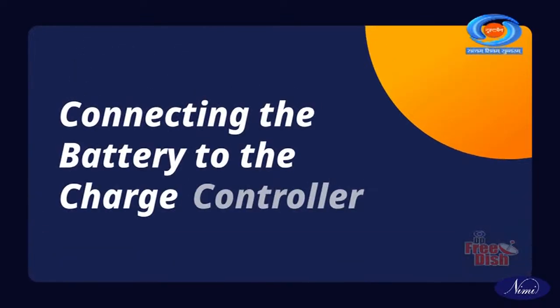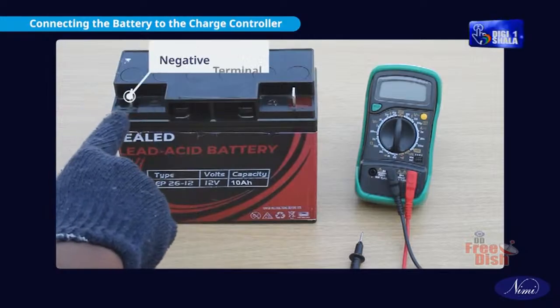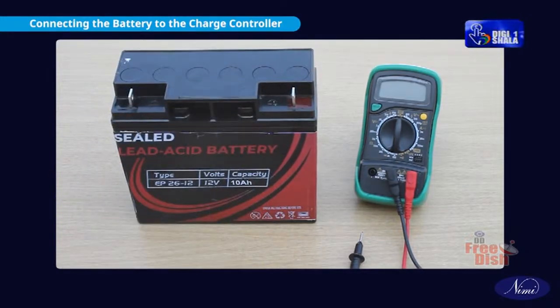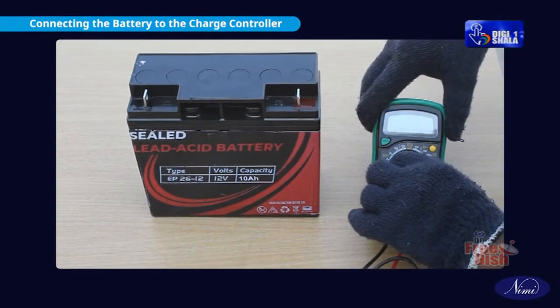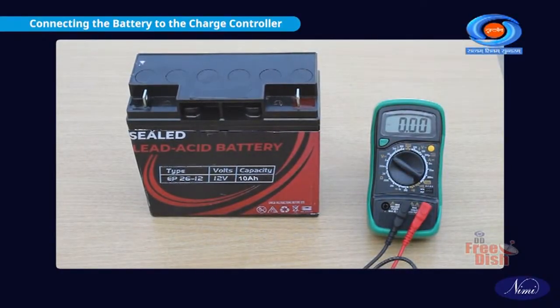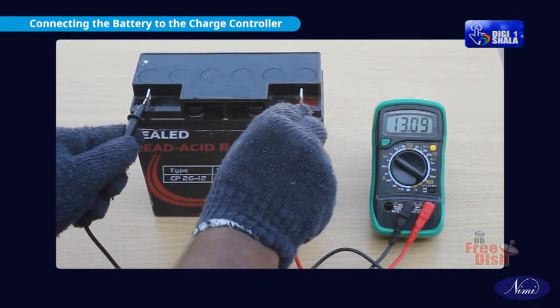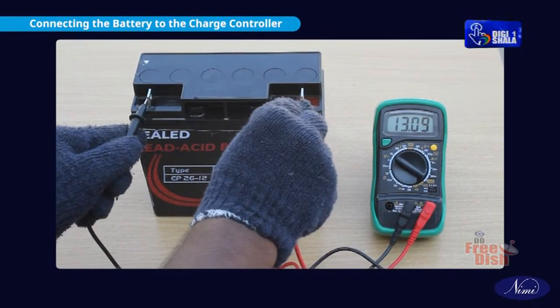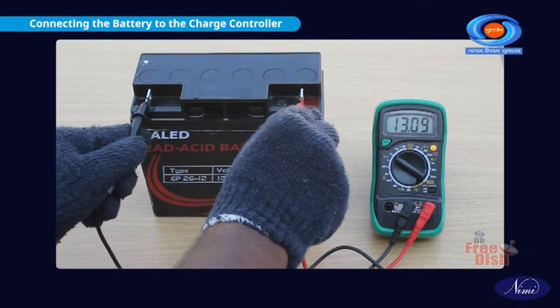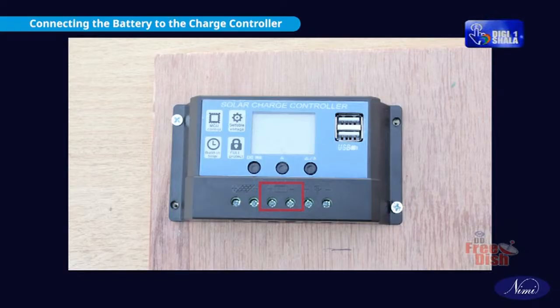Connecting the battery to the charge controller. Identify the positive and negative terminals of the battery. Set the multimeter in DC voltage measurement range with an approximate voltage of 20 volts and measure the terminal voltage of the battery. Ensure the battery voltage is not less than 12 volt. Identify the battery terminals in the solar charge controller.